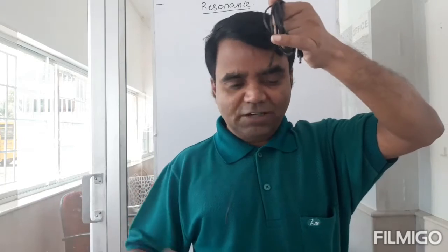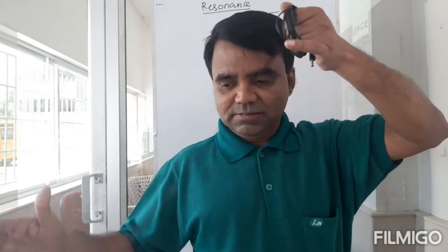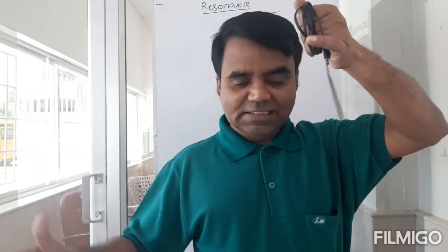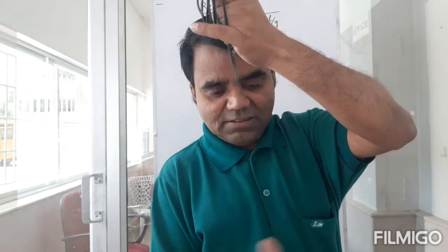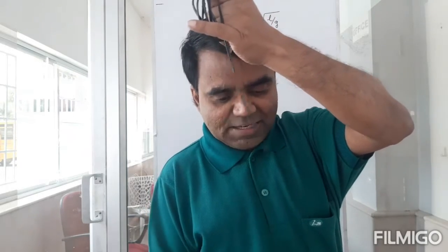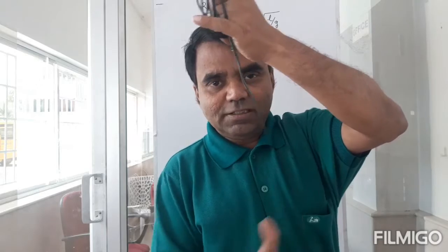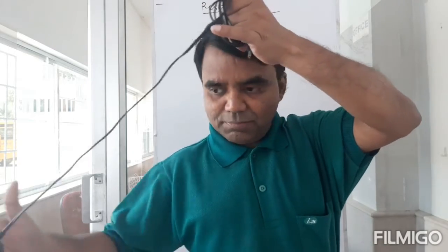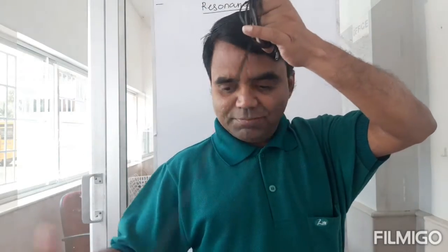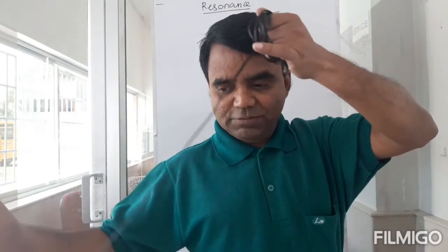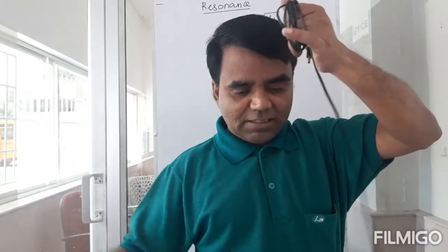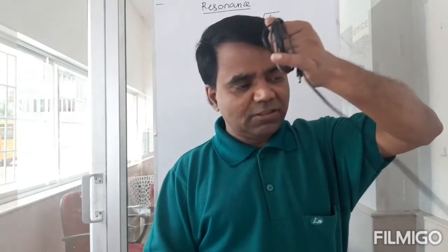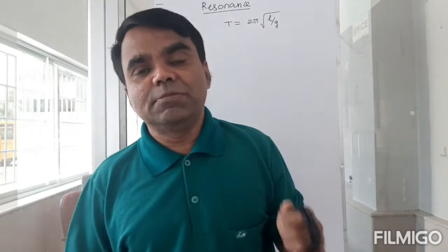Okay, so now you have resonance actually. What you're seeing is resonance. Instead, if I keep changing the frequency, then you see you don't have the same amplitude now. But if I allow it to come back, and then if I match this, you see, if the frequency of the external energy source, that's me, is the same as the natural frequency of this pendulum, then it has the maximum amplitude.